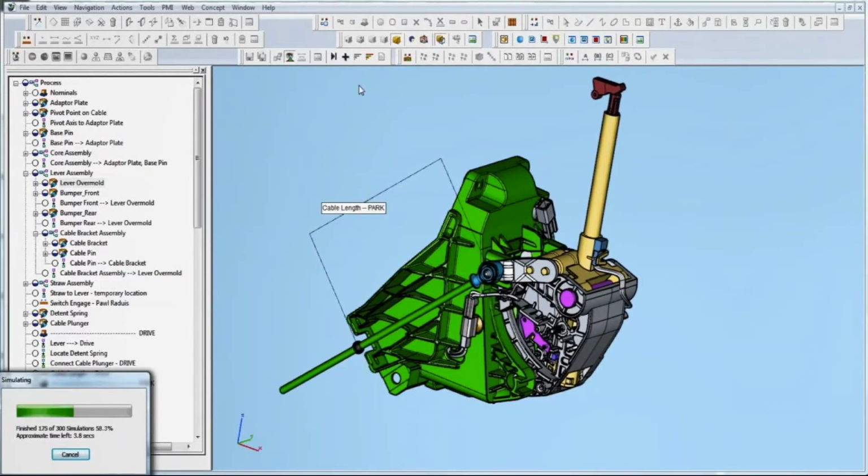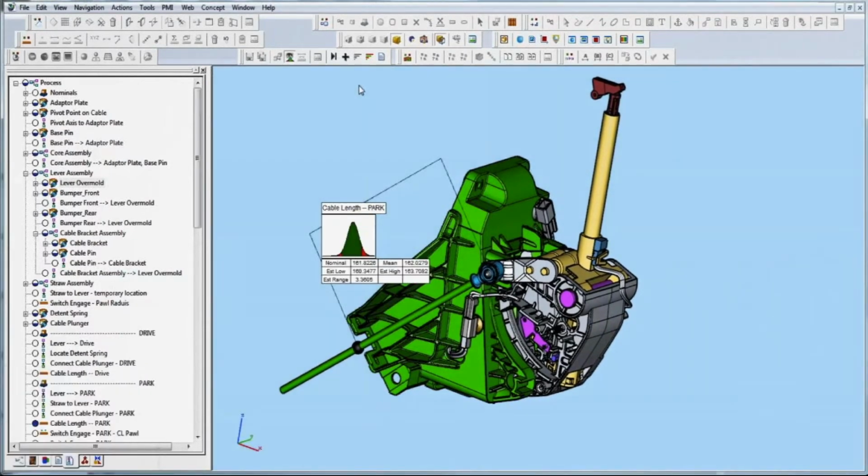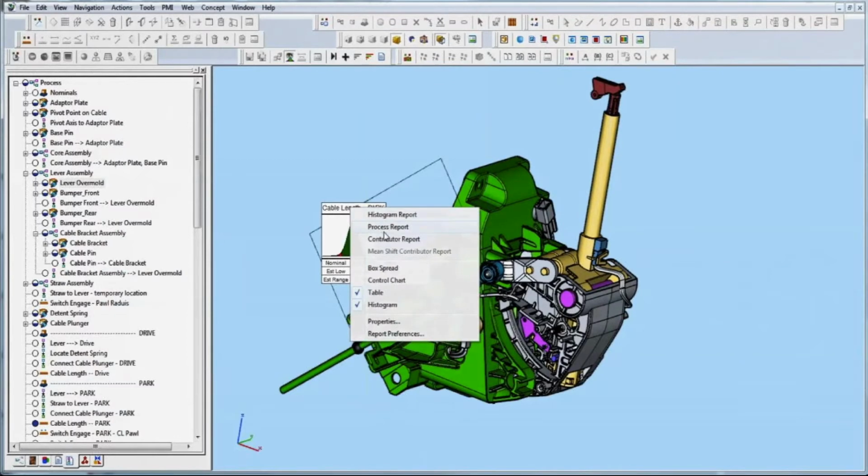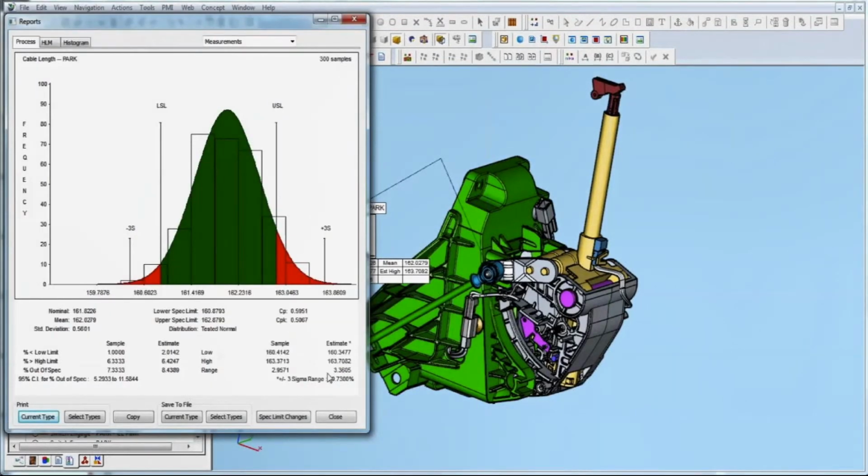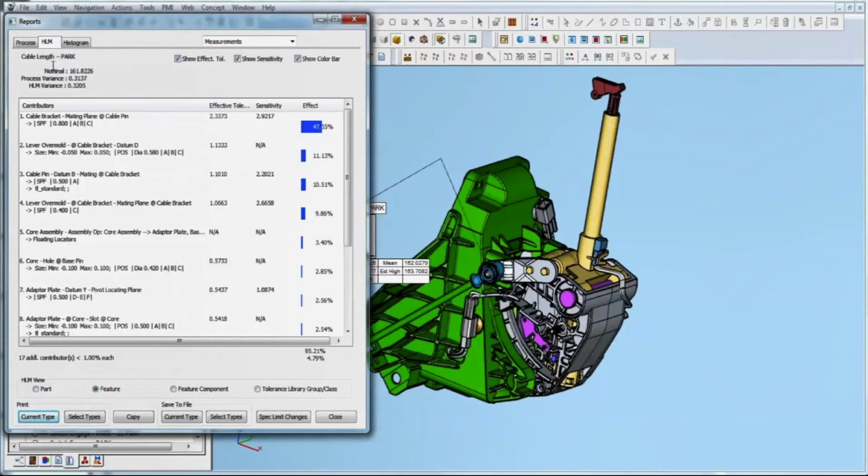So you see Monte Carlo builds here, the actual model's wiggling just a little bit. And what that's doing is giving us data that we can analyze. So here I'm analyzing. You can see I got 3.3 millimeter range. We wanted plus or minus a millimeter, so I exceeded it. 8% of the builds fall in the red area there. So my design and experiments tool, here's that one at 47%, is right up on top.